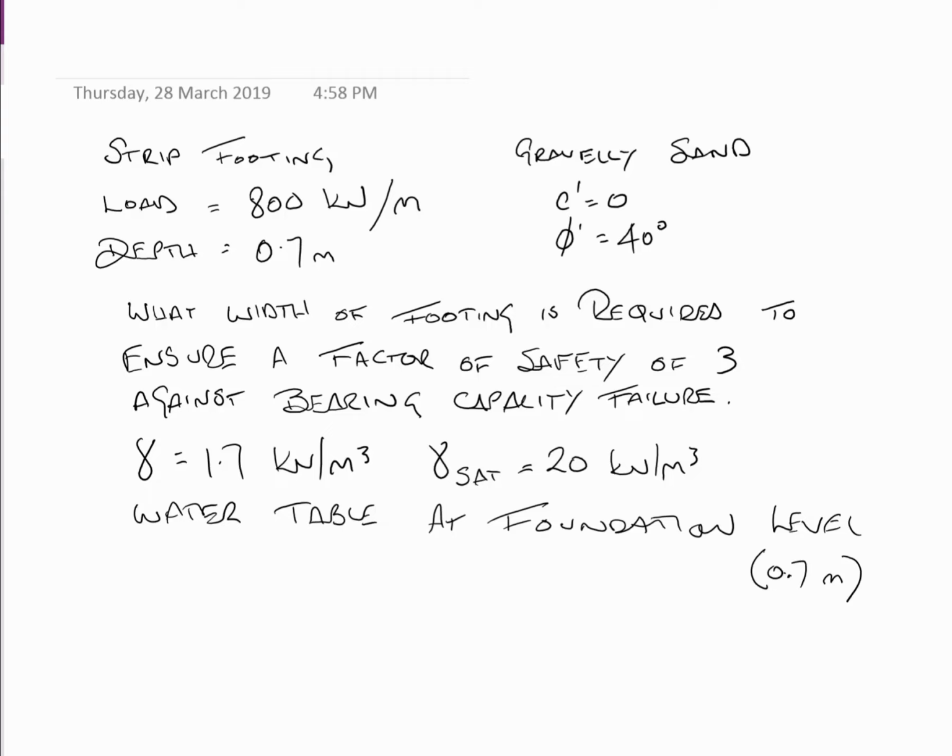Okay, here's one to introduce a strip footing to you and the concept of a factor of safety. So the information we're provided, it's a strip footing carrying 800 kilonewtons per metre run of footing. Depth is 0.7 of a metre. We're in a gravelly sand. C effective 0 and phi effective is 40 degrees.